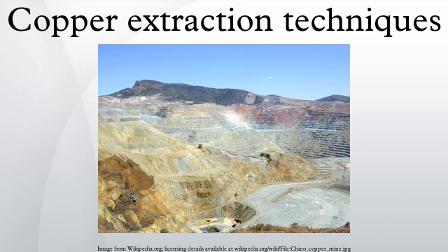Oxide ores. Oxidized copper ore bodies may be treated via several processes, with hydrometallurgical processes used to treat oxide ores dominated by copper carbonate minerals such as azurite and malachite, and other soluble minerals such as silicates like chrysocolla, or sulfates such as atacamite and so on. Such oxide ores are usually leached by sulfuric acid, usually in a heap leaching or dump leaching process, to liberate the copper minerals into a solution of sulfuric acid laden with copper sulfate in solution.